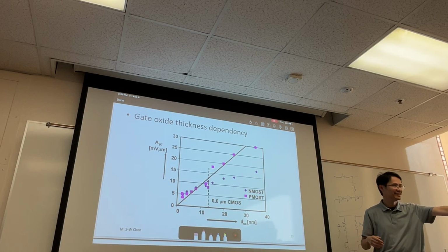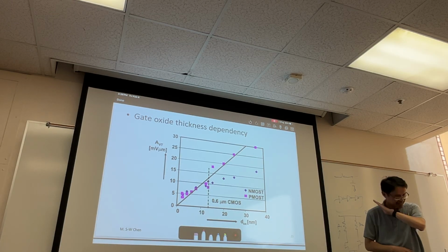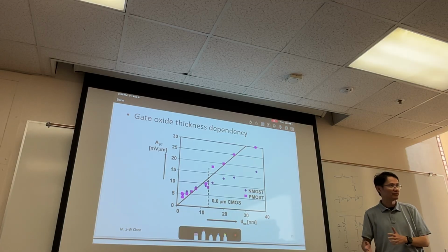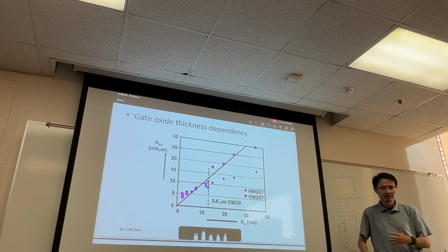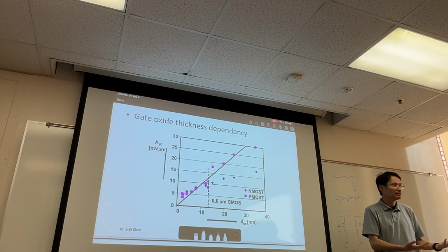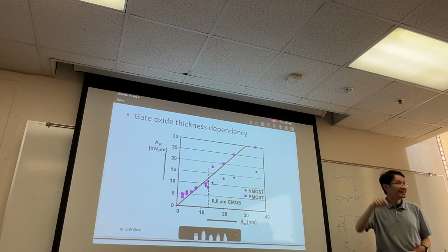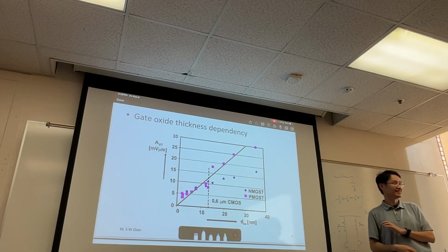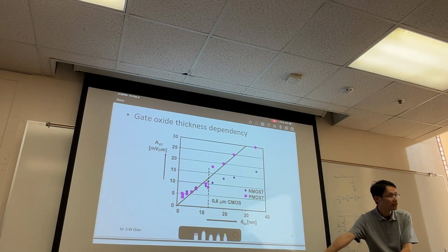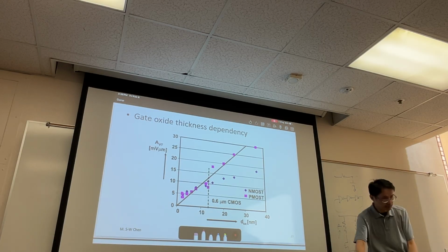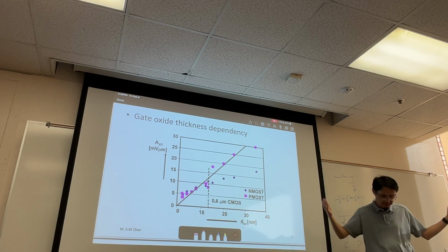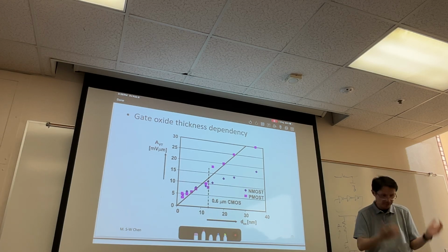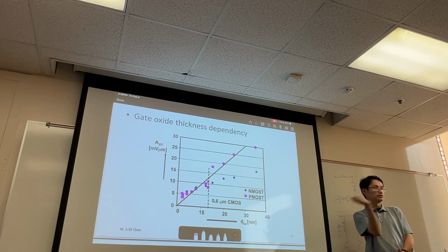Minimum size. You see that? It does not matter what technology node. Usually when they design the digital library, when they say inverter 1x, that means that you are using absolutely minimum size. That's why they keep going down, right? Your W/L, your layout becomes more compact, everything goes down. That's why digital guys are always happy.